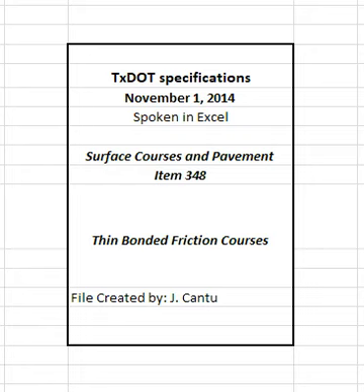The department will not pay for or allow placement of any mixture produced above 350 degrees Fahrenheit. Produce WMA within the target discharge temperature range of 215 degrees Fahrenheit and 275 degrees Fahrenheit when WMA is required.